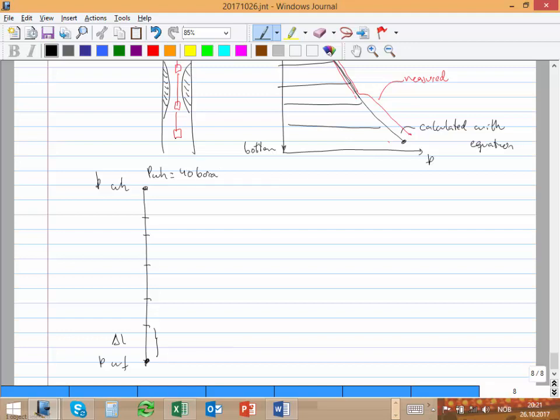And we know the equilibrium rate, how much was it? 2.85 e to the 6th standard cubic meters per day. That was the equilibrium rate. So now if I calculate this CT and this S, I can just use the tubing equation. I have P2, I have the rate, and I can calculate P1.